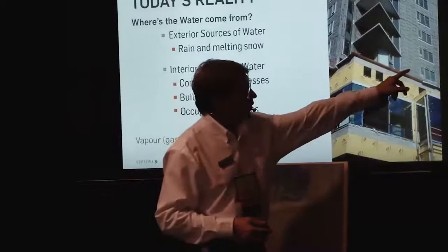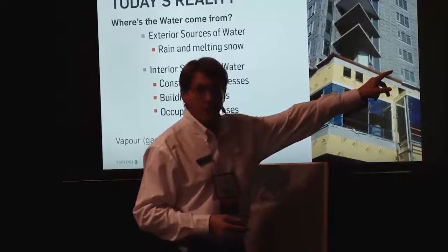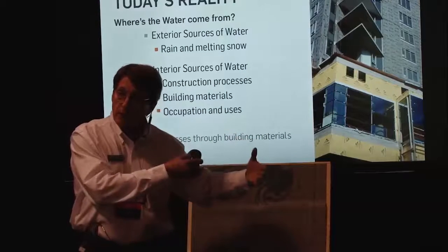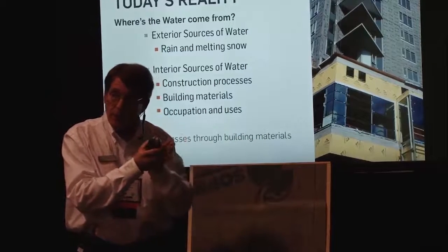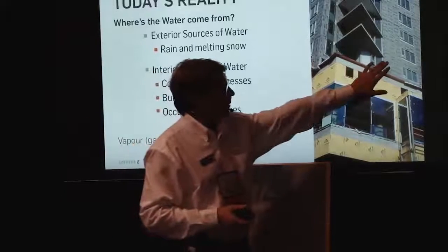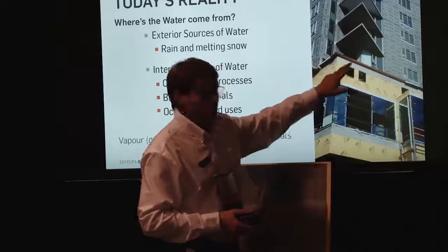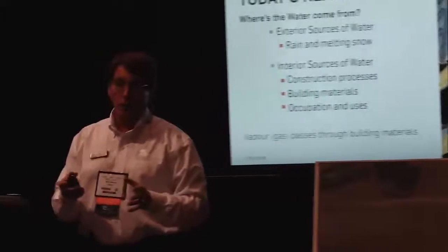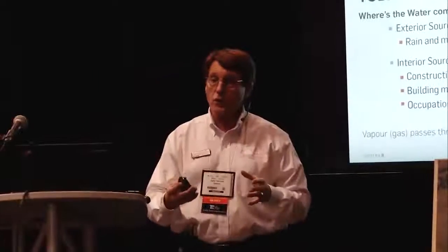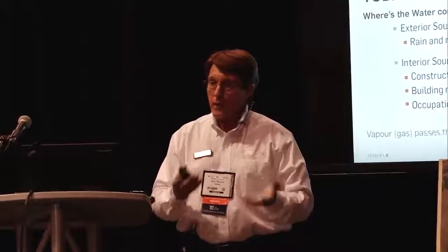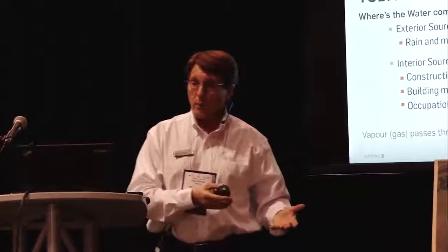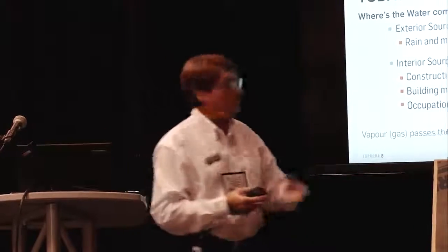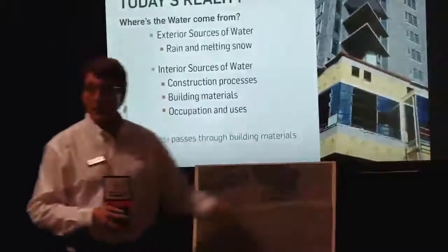This is our Super Seal stick VP on the wall here, over top of dense glass gold, so we can understand there would be insulation inside the stud space, insulation inside the cavity, marking this as a permeable material. But we've got this big hunk of concrete here, we've got lots of glass. So throughout the building structure, the materials that we would attach to have both the opportunities of being either a non-permeable type product or permeable, and some of those we don't have a decision on what they're going to be because of the nature of the beast.